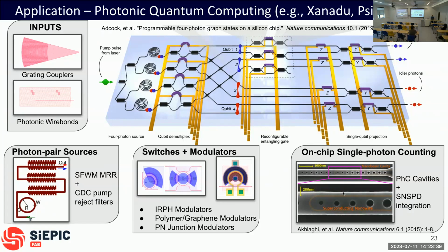And then the other one is the single photon detectors. These are based on superconducting materials, so there's a connection to the superconducting field here. This is basically extremely thin pieces of superconducting metal deposited on top of the waveguides that we're talking about. And again, they evanescently couple and absorb that light through the metal.